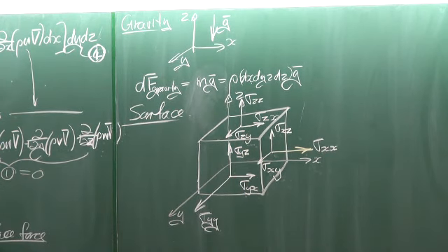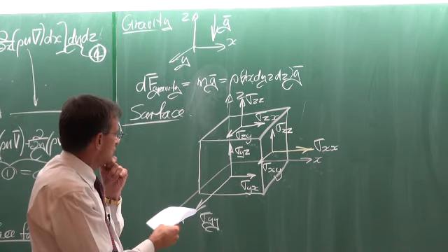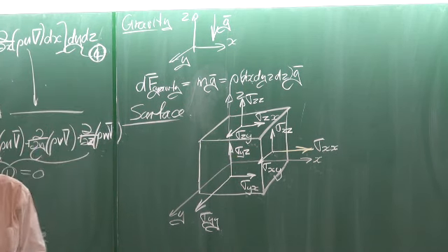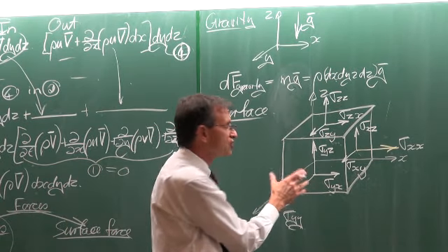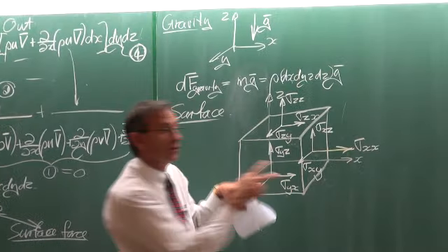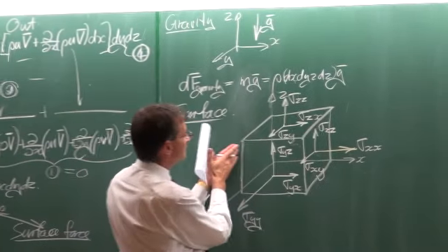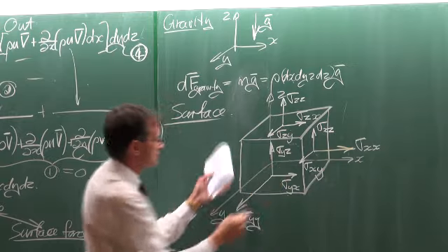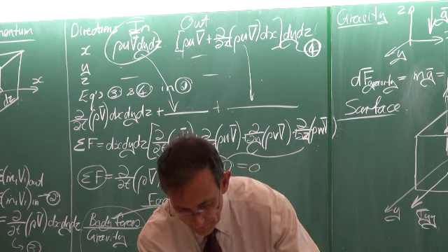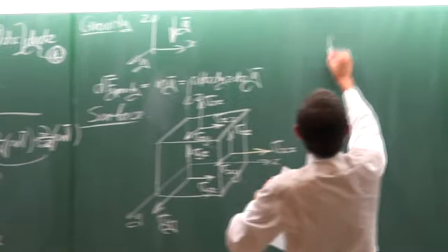So it looks very complicated, but what is important to always remember when we look at these stresses is that it is not the values of the stresses that cause the force, but the differential that causes the force. The difference in values from this surface to that one causes the net force on the volume. Now we need to look at this control volume like that.